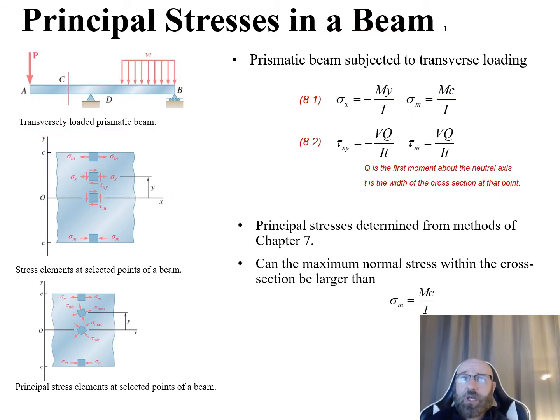Now taking a look at our σm, we can recall from previous chapters and modules that within our elastic limit, the stresses on a small element with the faces that are perpendicular to our x and our y axes reduce to a normal stress here of our σm if the element is at the free surface of our beam.